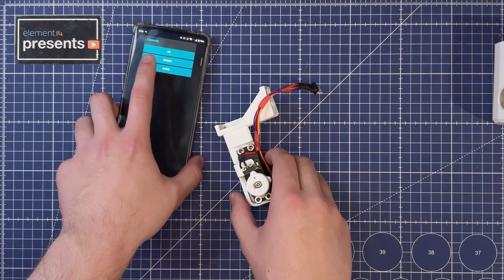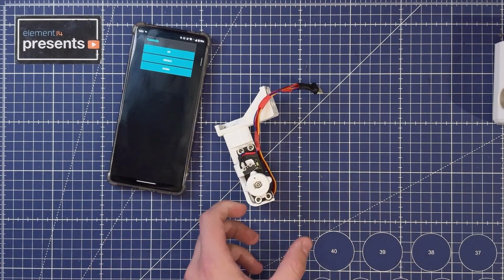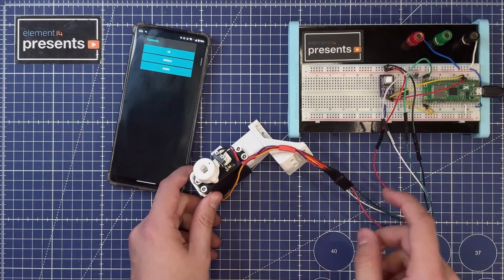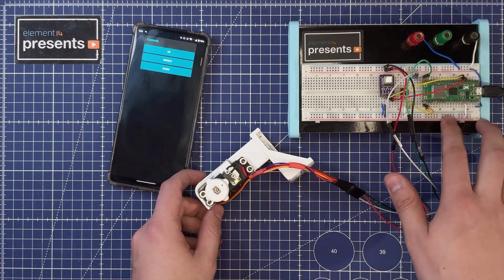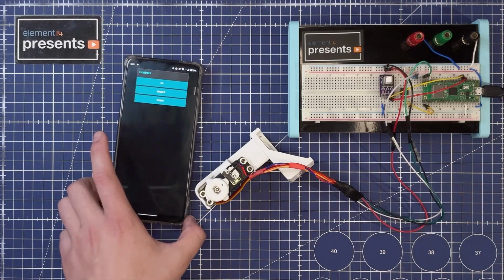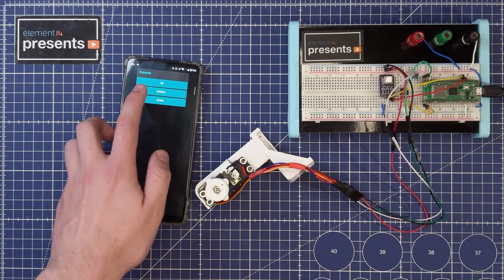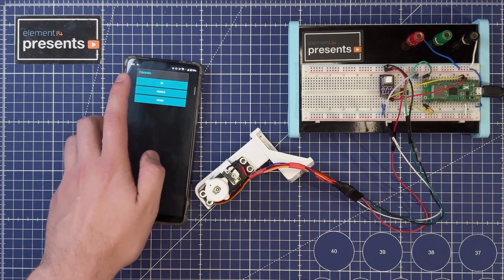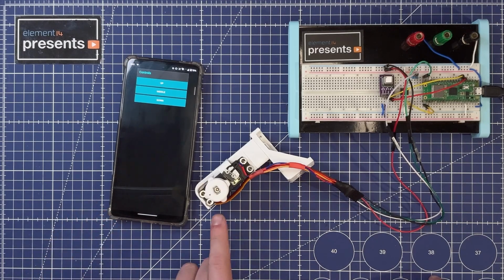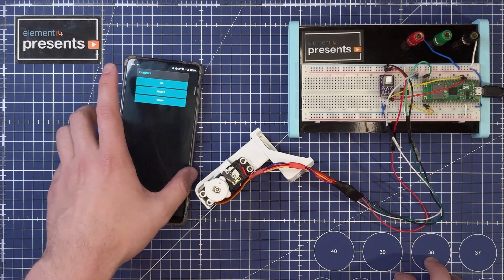I've just added a few buttons like I showed you before for the LED. So let's just connect this to the Raspberry Pi Pico. I've connected it to the Pico. It's running similar code to the first test, where it just accepts these button presses as inputs. So if we press up, for example, I've put a set amount of clicks that it needs to go before it stops. You can see it spinning right here. So it stopped, so now it thinks it's in the up position.